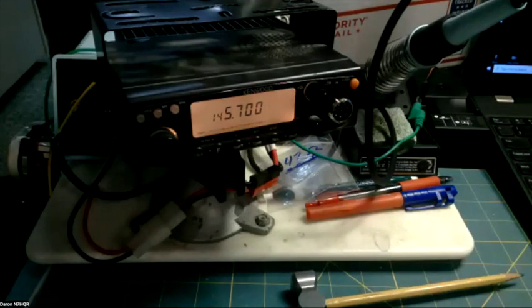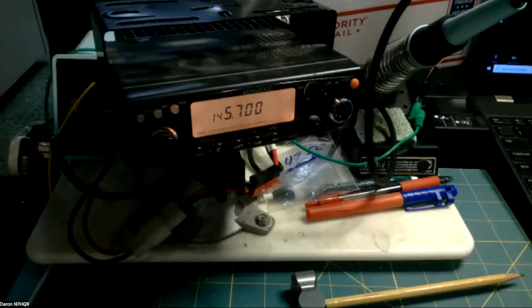So now I'm going to increase signal strength. So that starts to hear at about negative 120 dBm. So that'll kind of be our reference point where we opened the squelch on this radio. Now, are you using a signal generator to do that? Yes.